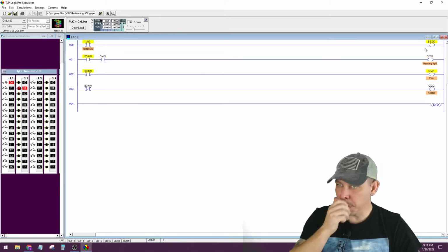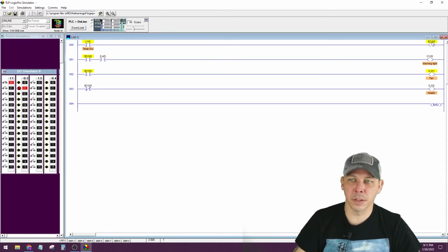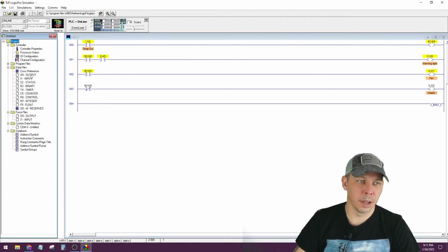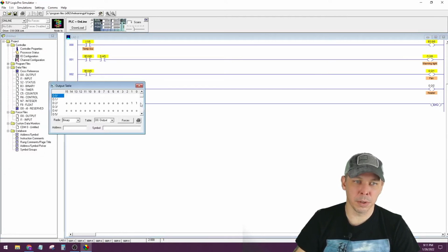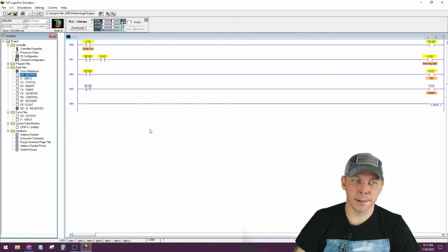So you could do the same thing like you do with relay logic, and this could just be an output. Like this could just be your lowest possible output location, but that's a physical output on your PLC. There's a screw terminal on your PLC or on your output card that's going to change state. It's going to send a signal out through that if you use an actual output in your output folder. These are all actual outputs that are going to change state on the exterior. It's not an internal bit that you're using.